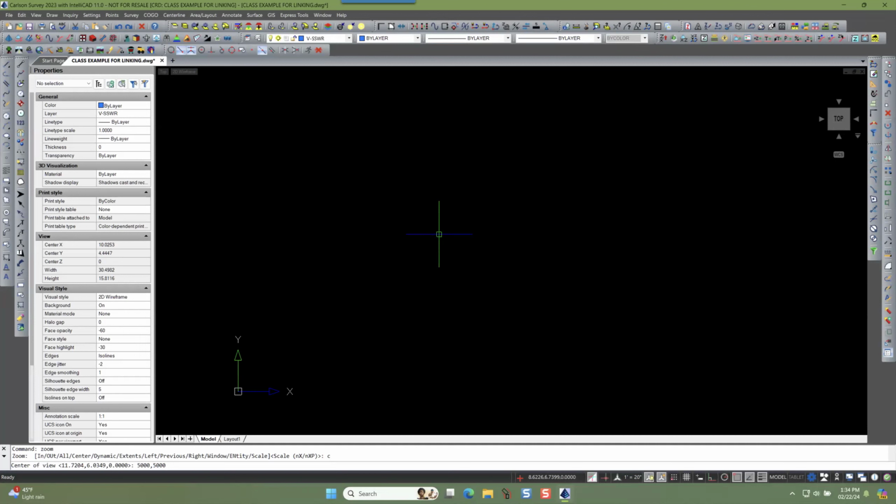And I'm not going to set a Z elevation, so I'll just leave that part off. It's optional. I will hit enter. And now it's going to ask me for a zoom factor or a view height, and the angle brackets tell me that's my default number, because the last time I ran it, that's what it was.